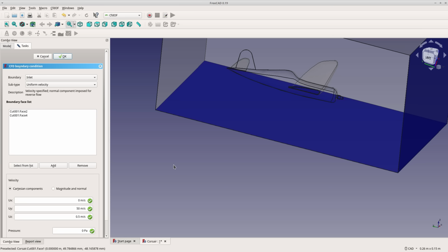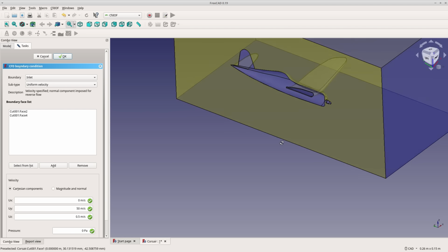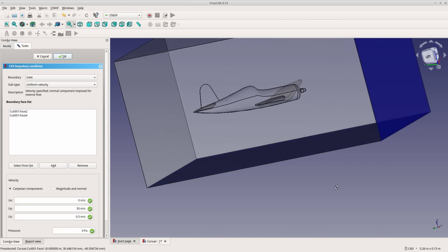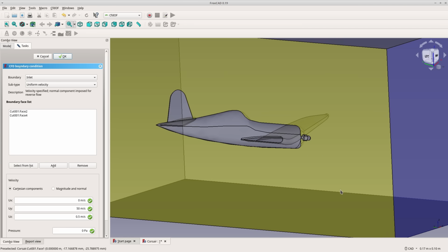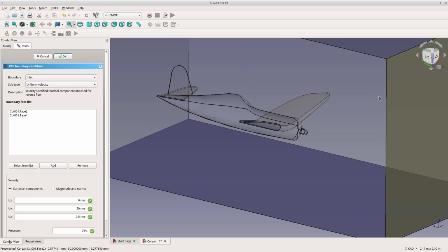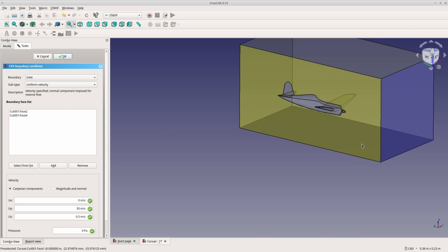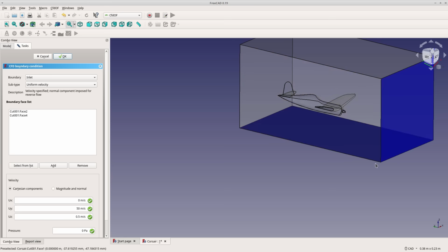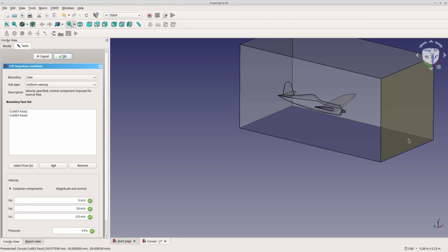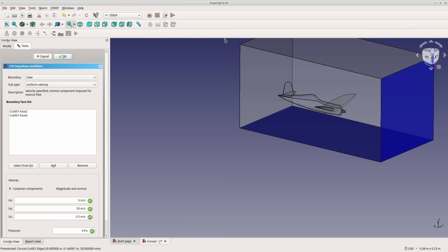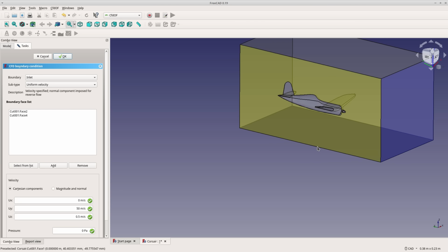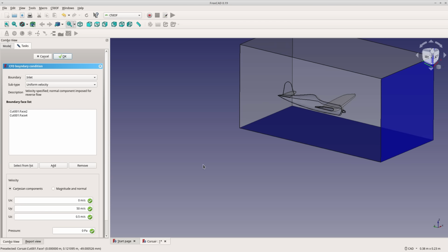So we're coming up at a slight angle, probably won't be that noticeable, but that is how you can select your faces. Because I didn't just select my front face, I selected my bottom face, and that's for a uniform flow across the cross section. If I were to just specify the front face and have an upward angle of the air and have this bottom face be a wall, then it just won't flow quite right.